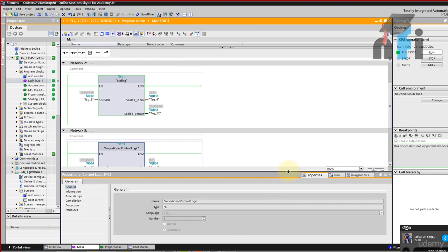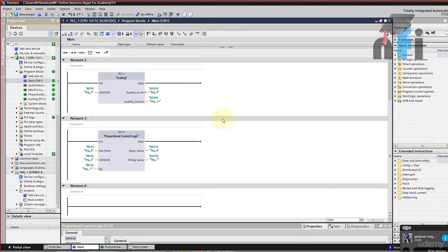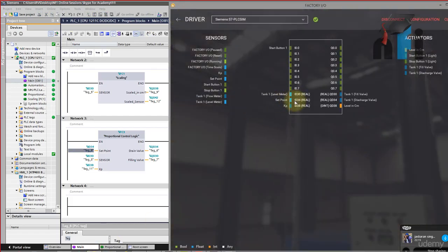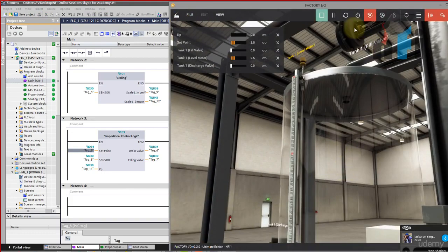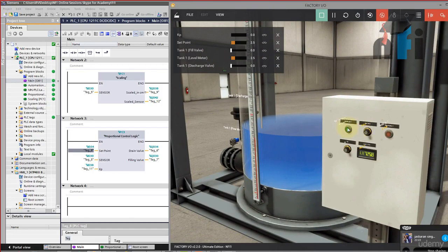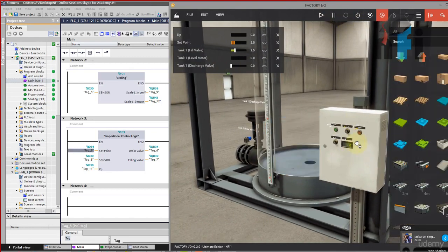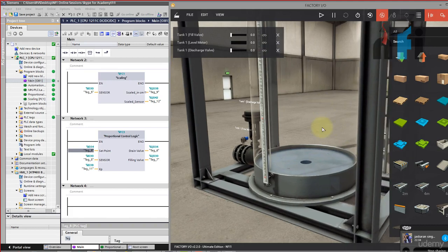So here, that's the proportional control logic. Go offline. Now, this ID34 was the set point before. So this ID34, if you notice here, was a set point coming from the panel. Since we are replacing the panel, we do not need ID34 in the program. So if I remove this panel, I'll go to stop, I don't need these buttons. So we don't have any panel here now.